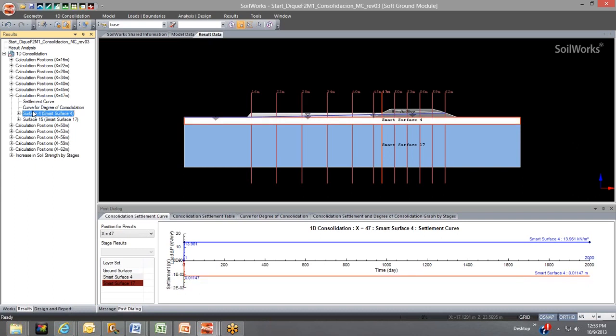Just double checking to see if there's any changes, but it appears that all the settlement in this particular project is immediate. So after immediate settlement, what the program is telling you is that there won't be any other settlement afterwards. So even a couple of years after the immediate settlement, if none of these conditions change, then the settlement or the displacement will be the same.